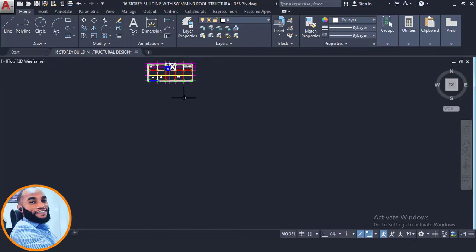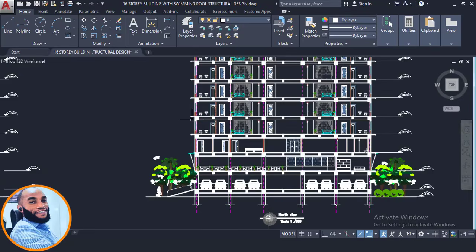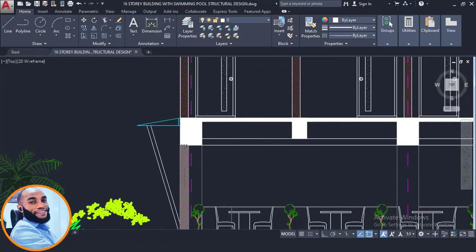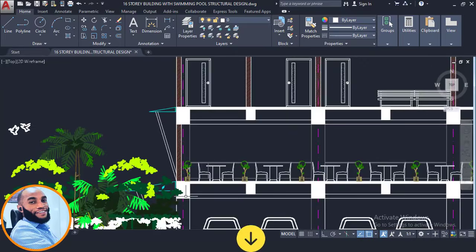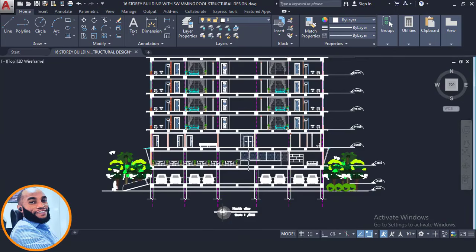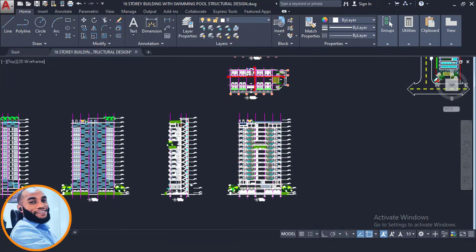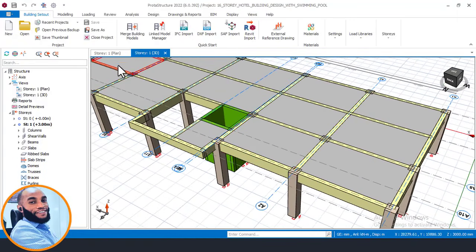If you look at this place here, you will see that most of these beams have a wall. This thing here is a wall symbol, so there is a block wall sitting directly on this beam here. So we are going to add those wall loads on the beams. Okay, so let's continue from what we are to do today, which is to insert wall load, insert cantilever slab, and then also insert our story.